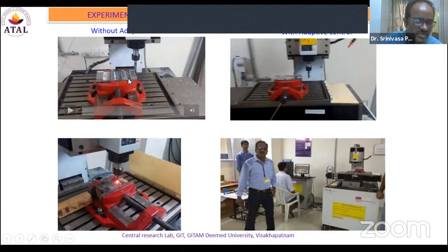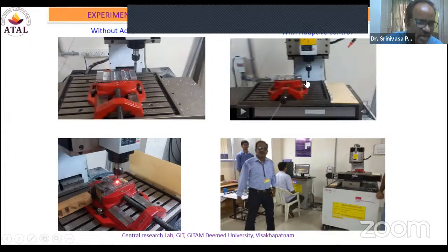When an air gap is found, even during the air gap, this machining process continues with the same feed rate, same depth of cut, and same speed. Whereas in this particular video, with the same part geometry, it is able to double its feed rate when an air gap is identified. That is indicated with the help of the presence of vibration.